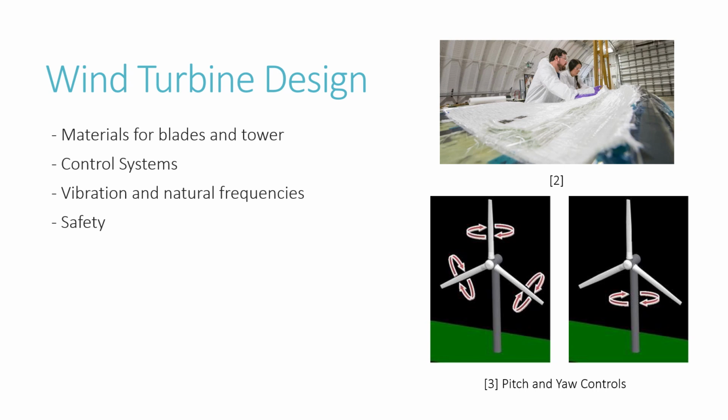From a safety standpoint, turbines are designed to have cut-in and cut-out power outputs. To ensure that the turbine will not exceed the maximum power and braking capabilities, turning the nacelle and blades with yaw control away from the wind or blade pitch control to rotate the blades and increase the angle of attack, which produces and uses stall to slow the blade rotation, can be implemented.